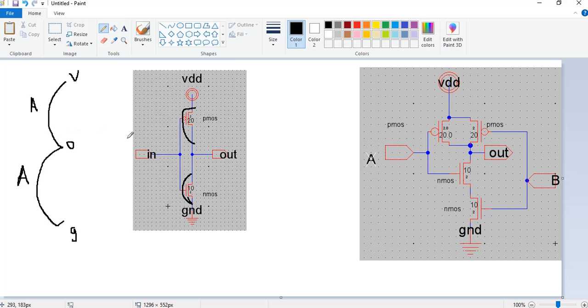Fine. Now, the rule says look at the path that each transistor traverses, touching all the nodes and not repeating the paths. Pretty confusing, but let me make it very clear. The agenda here is to traverse from one end to another end, once for PMOS and once for NMOS, in such a manner that all these nodes, meaning these points, are covered.